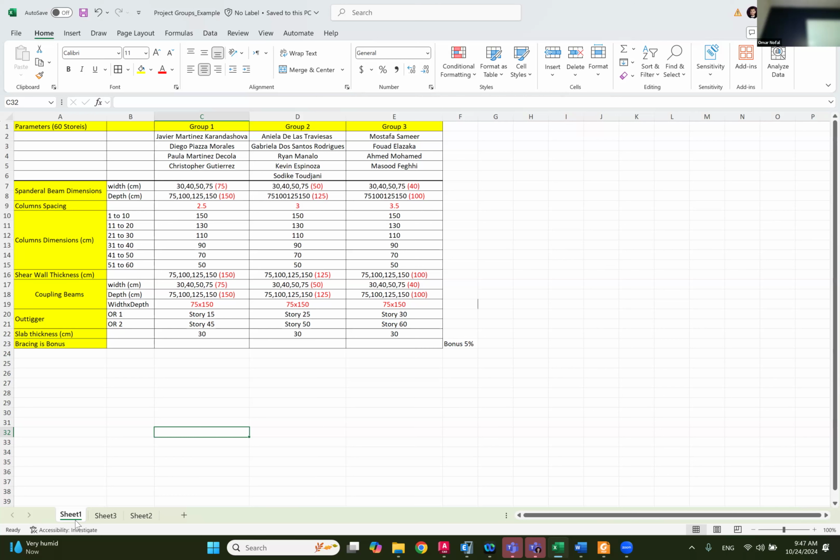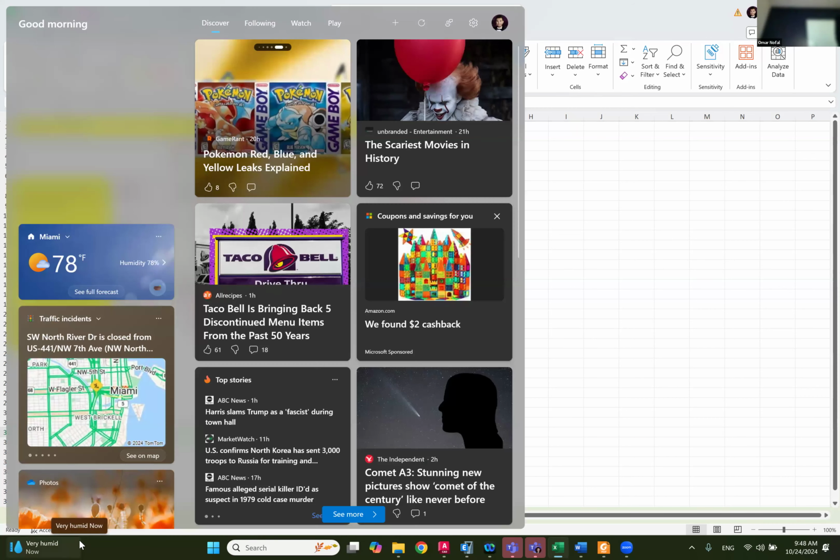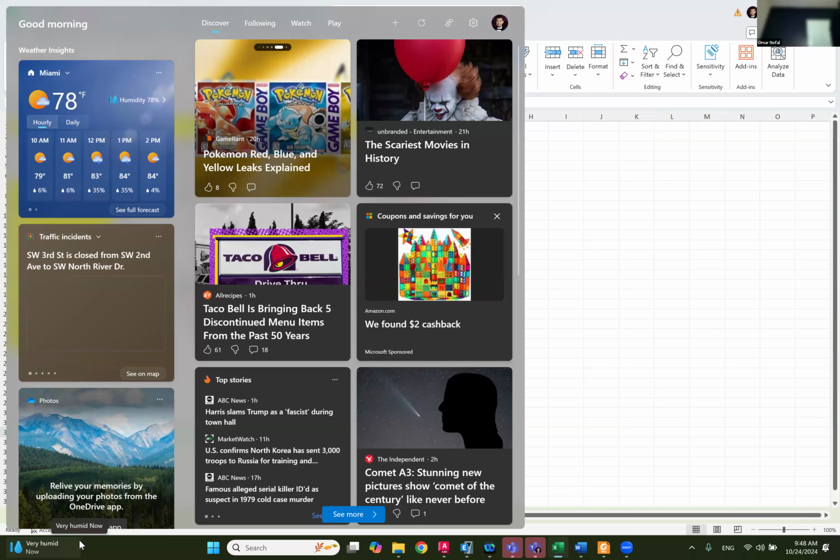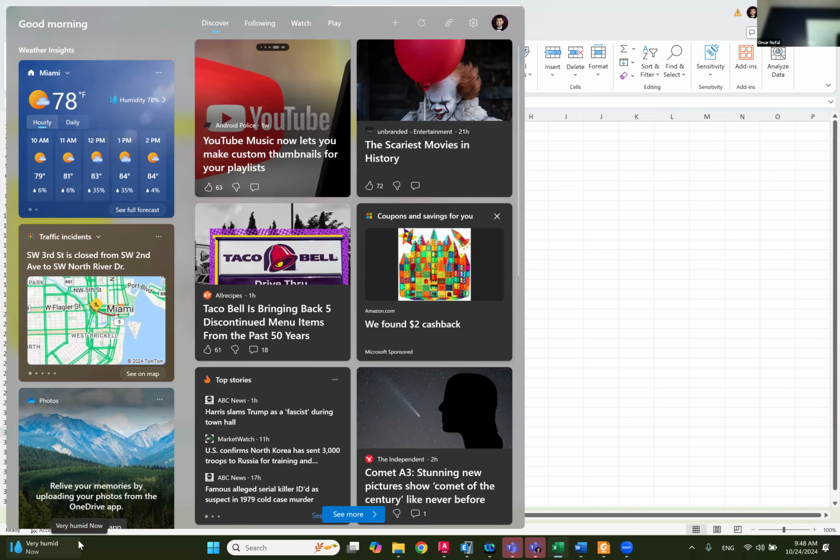Yeah, I don't think that you have a lot of options, but maybe you can. What I would do, I have my building, I already have the base model. I just try to connect each story with a member. The dimensions you want, yeah. Maybe you can use the column dimension, you can make a steel beam. We only need the stiffness, not whatever the cross section is. We are not doing design, it's just analysis.